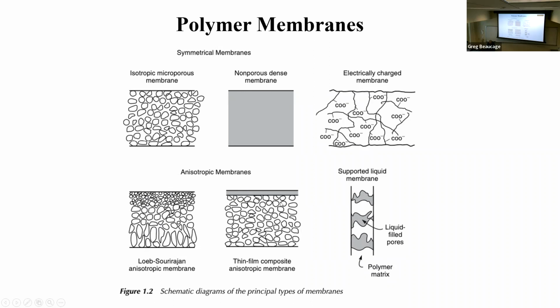And then you can also take this kind of membrane and do a Langmuir-Blodgett film, and then deposit it onto like a polysulfone substrate that's porous. Or you can just make porous membranes for different kinds of separation and change the pore size. And then there's these other kinds like sulfonated polystyrene or fluorinated, so you can have anion or cation transport membranes for like dialysis, or removing salt from water, electrochemical salt removal.